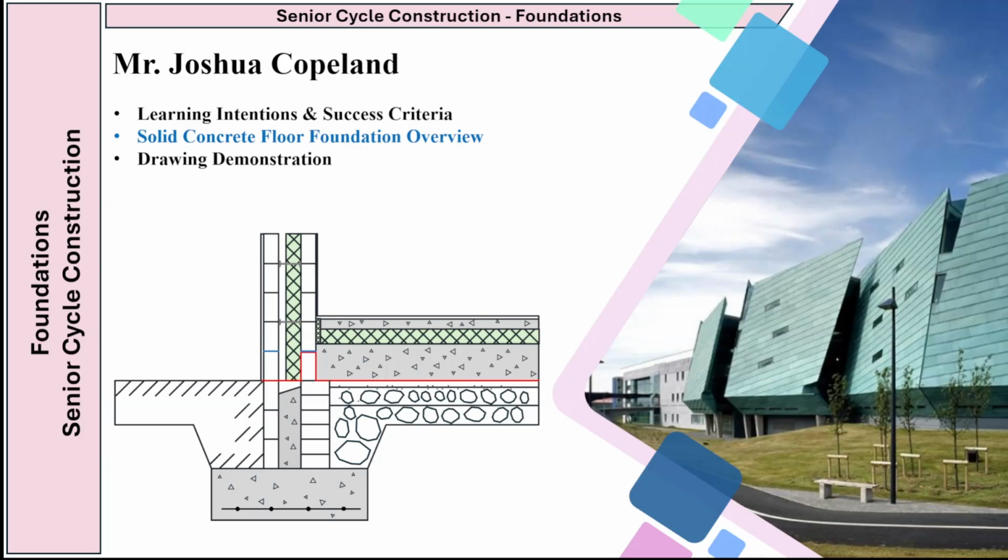Before we wrap up the video, let's do a recap. Our learning intention was to describe and draw a solid concrete floor foundation, and our success criteria were to identify the layers, explain when it's used, and draw it accurately to a scale of 1:10. We learned that a solid concrete floor is strong, durable and low maintenance, but they can be cold and difficult to access for repairs or services. They are commonly used in a domestic building on firm, dry ground.